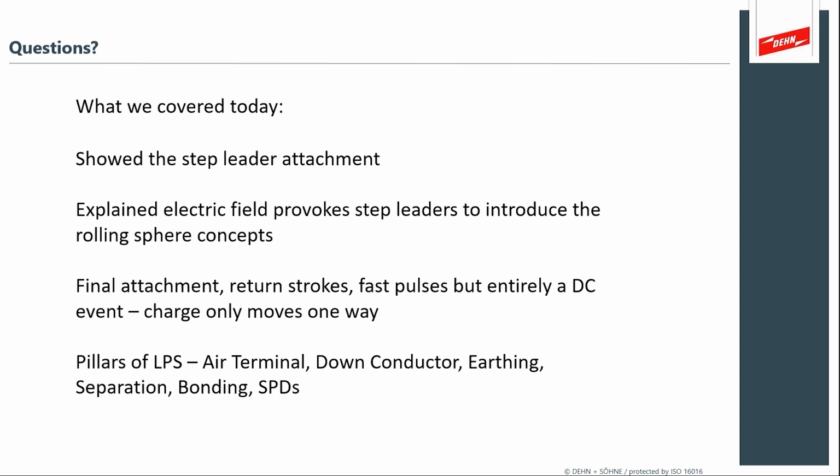And another point I want to mention here is that if you do have ESE air termination rods or masts in your facility, you can employ the IEC methods to calculate what would be the IEC zone of protection that you can receive from these ESE devices. It will be significantly less than what the ESE manufacturers would say it is, but at least it's then based on an IEC method. Anything you want to add about ESE technology and IEC methods, Mark?